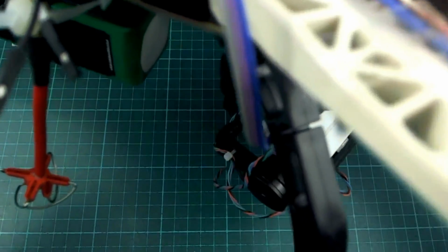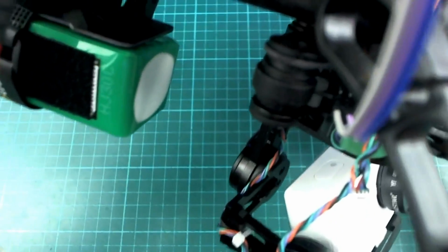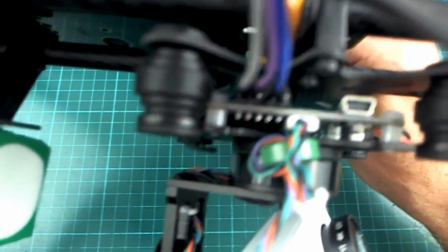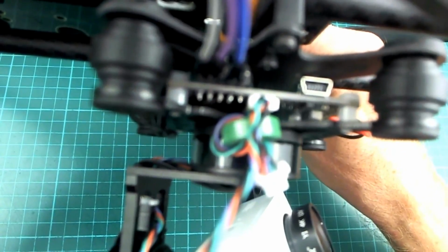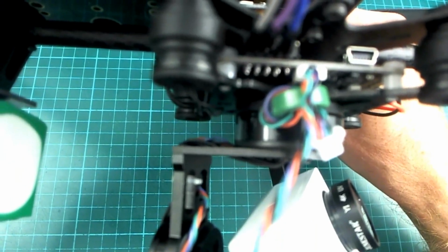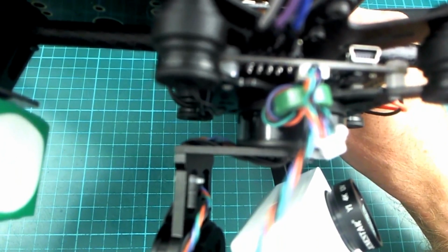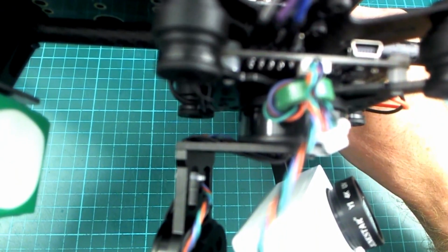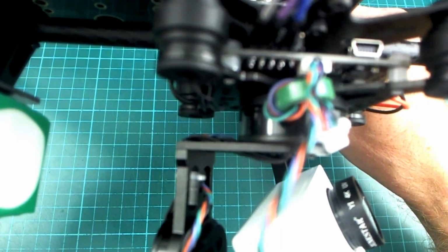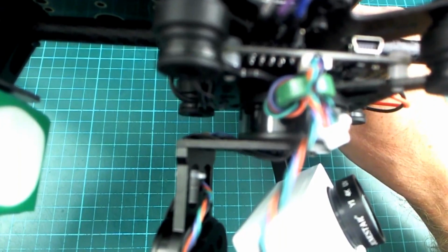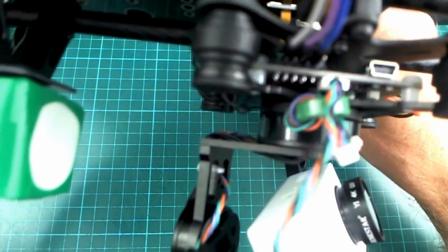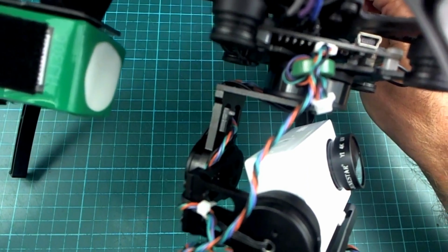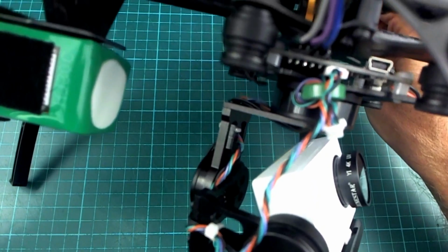And this is a bit awkward to try and show you, but if I turn this carefully, we'll see that those are going into the gimbal control board at the top of the gimbal, and those are used to direct the gimbal pitch and yaw so that the camera points at the tag while the quad is flying. Of course, you don't need to have a camera gimbal to do any of this. It just gives you a nicer result if you do.